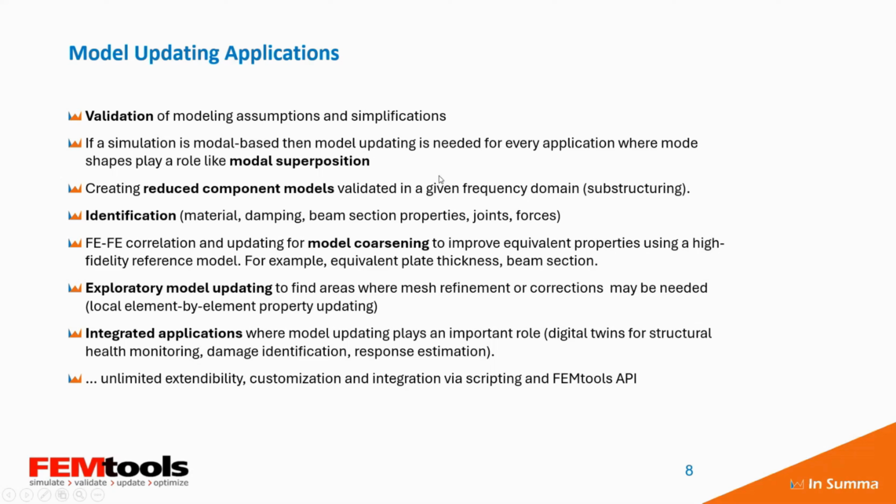So the modal base is the basis for the response simulation, and it is logical that we validate that modal base before continuing. It can be used for creating reduced component models that are validated when they are added in an assembled structure.